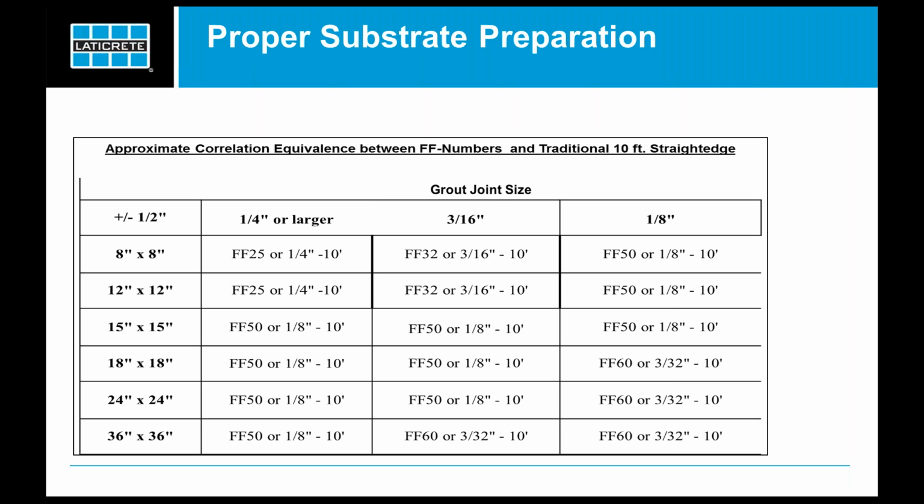So what we do is we try to encourage specifiers to carry a little extra in their budgets for additional surface preparation, especially when using these larger module tiles. That's really the only way that you're going to be able to get a floor that's flat enough to receive these types of finishes. We know that's not always something that specifiers want to hear, but unfortunately it is a reality. These floors do have to be flat enough in order to receive these materials.